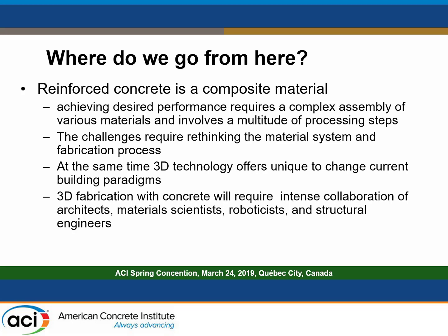But that's a challenge because that requires rethinking the entire material system. How do you make a cementitious system more tolerant to the increased heat caused by the fact that you are trying to print hot epoxy around the wire? You would have to change maybe the process, how you deliver the material. Do you mix it at the nozzle or do you mix it ahead of time?